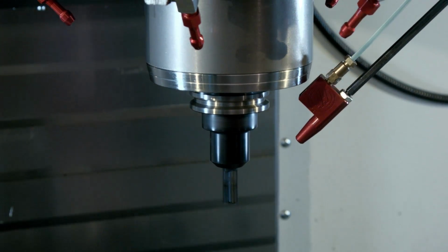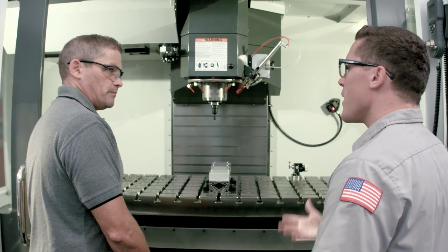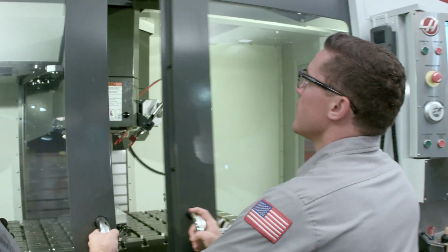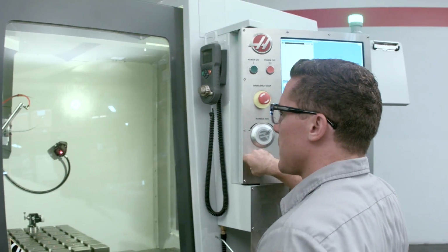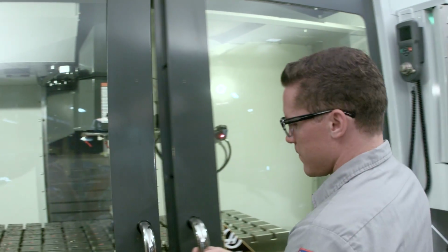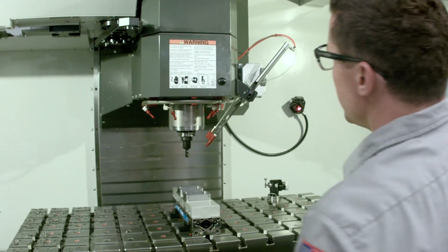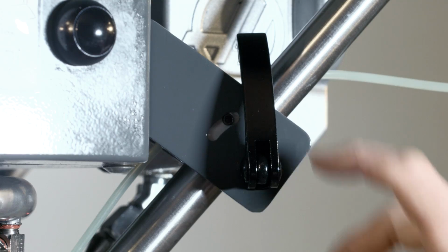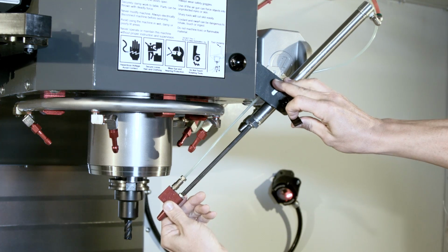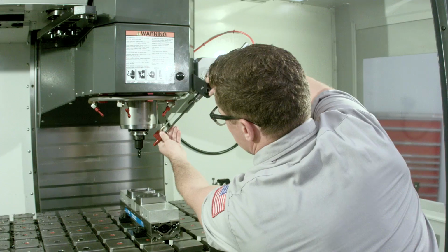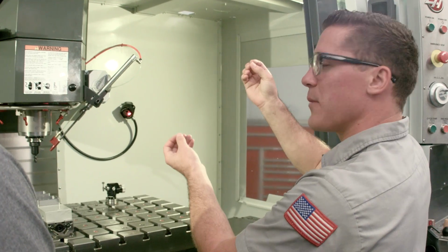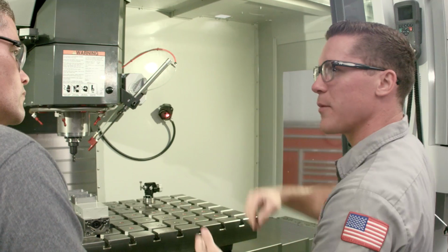Can you show us some of the things we need to know about setting up the MQL system? You bet. Let's start by adjusting the atomizer nozzle. First, I'll close the doors and activate an M83. Now I'm going to adjust the atomizer nozzle about 1 to 3 inches away from the tool. So you've got your distance set, and it looks like you've got the nozzle pointed at the tip of the tool. Yeah, so typically you'd want to point the nozzle towards the tip of the tool, but other times you may need to move it up towards the middle a little bit if the tool is partially obstructed.